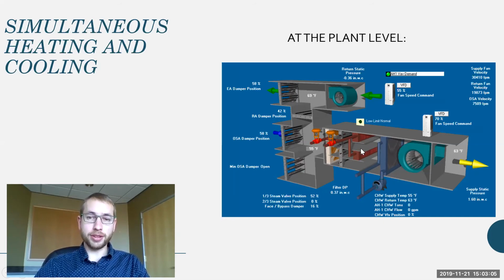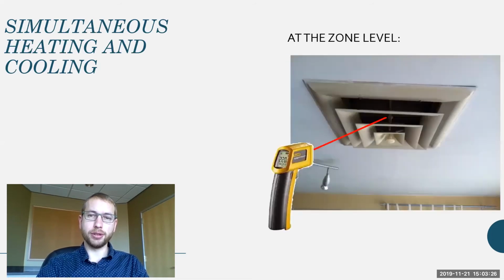But sometimes the valves get stuck and you will still get this hot coil, sometimes steam, passing through this all the time, all year round when it's not needed. So that's one point to check within an energy audit, is to make sure that you don't have simultaneous heating and then cooling at the main rooftop unit or plant level.